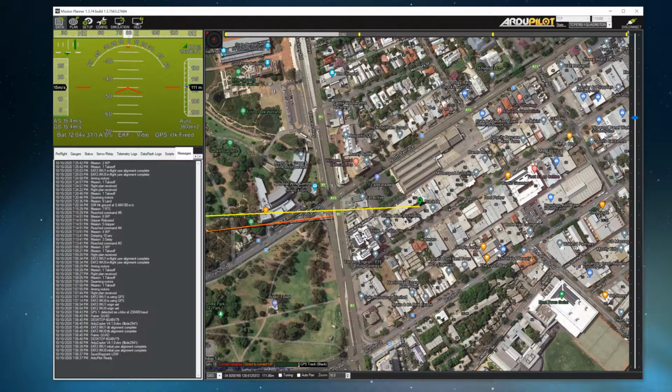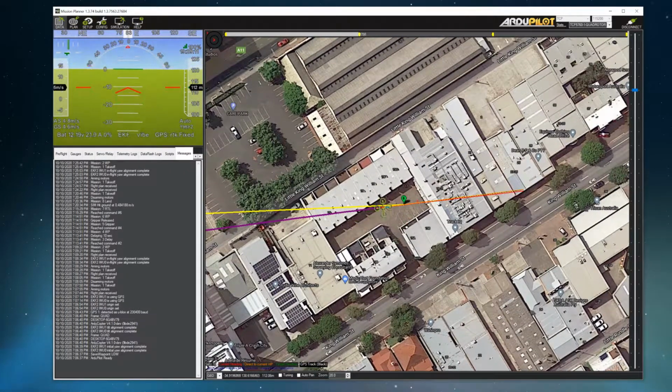Just a disclaimer, after I've set the mission, I haven't touched the keyboard. This is doing it all by itself. Once the drone reaches its waypoint, it will lower to a height of 20 meters off of the ground and release its payload. After that, it will hover in place and rise once again to a height of 100 meters.